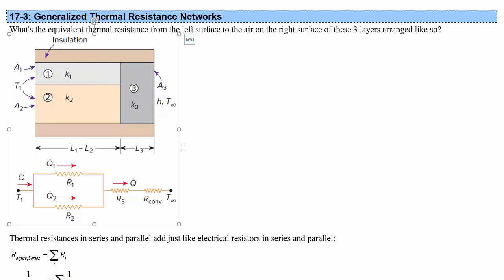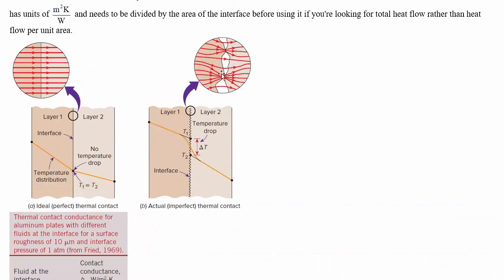But there's an implicit assumption in this, and this is really assuming that the heat flow in this object is kind of uniform from one section versus another. If it's much easier to flow through this k1 than it is to flow through k2, then really what you'd find is that the streamlines wouldn't just be in the conduction direction, they would sort of spill out into k2 towards the end, so you can have more in here and it'll generally equalize a bit more as you go into k3. Think about this picture here to get an idea for how that would work.